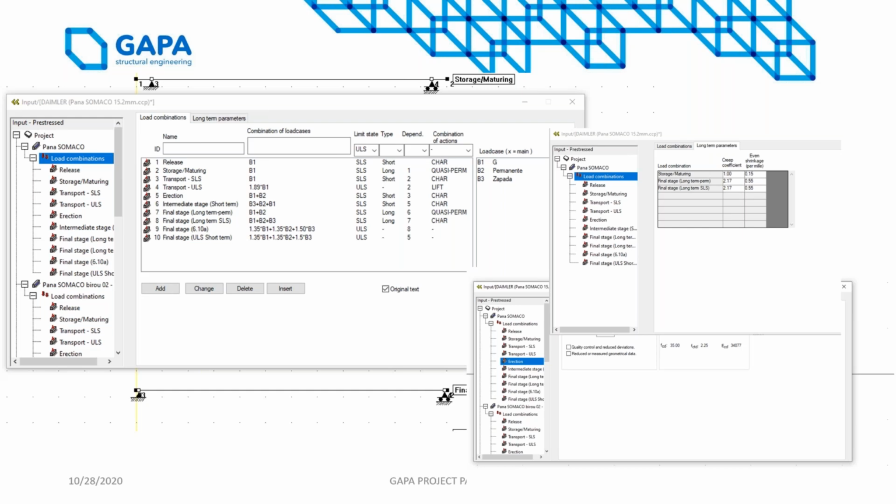And this has to do with the fact that early, when the precast element is young, some of the pre-stress force has not vanished through creep and relaxation. So having a larger pre-stress force might actually lead to higher stresses in the compression zone of the purlin.